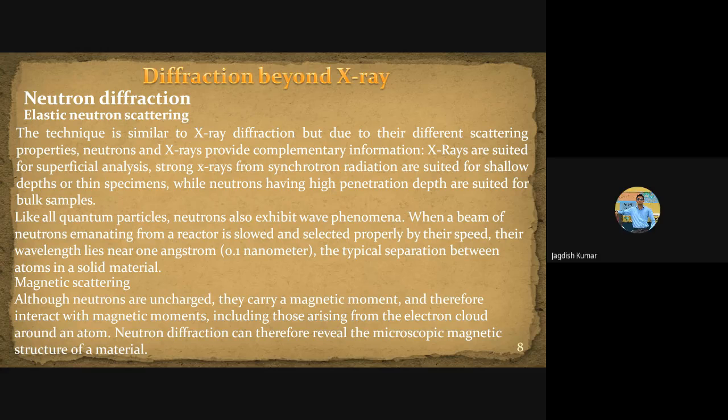Then those two diffraction patterns will differ from each other, and the peak shape parameters, when we calculate from Rietveld refinement of these two extreme cases, will be different. However, whenever we are doing X-ray diffraction at room temperature, because everything is at a specific temperature, usually we fix those parameters because we are not doing a temperature dependent X-ray. So we can fix that to be constant, and we don't want to bother about that.